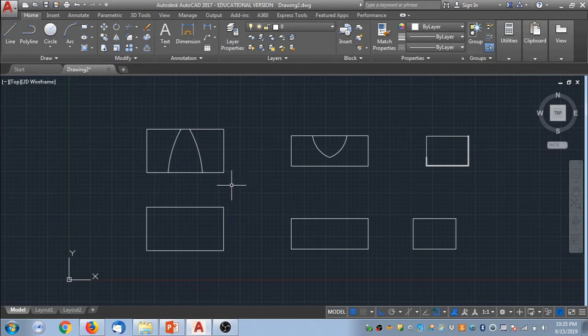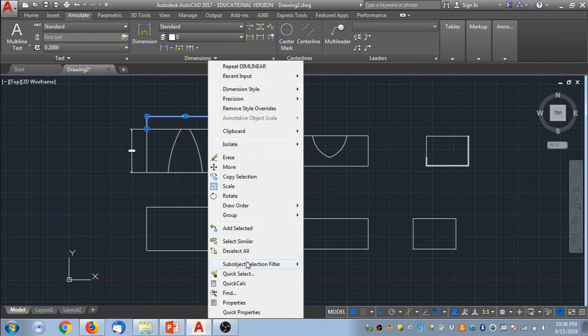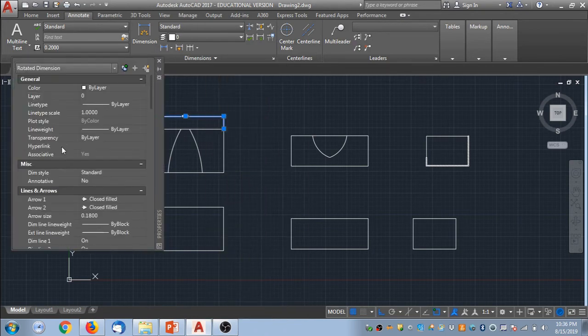The thing we need to do now is give everything some dimensions. Dimensioning is significantly easier in here. Here you go to the annotate and it gives you dimensions. I find the automatic dimension, which is the dimension with the sunburst in it, to be very hard to use. So I just am using the linear dimension tool here because we have rectangles, everything will be in a straight line. And I basically just go through and click on the beginning and the end, and it gives it a dimension.